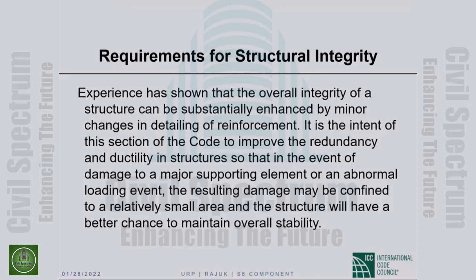Okay. In footings or pile cap, where should we place the temperature or shrinkage reinforcement? In the top of the footing or pile cap? I specifically covered this; the answer is the same as for mat foundation. It is up to you. If you think it will do the most good near the top surface, that's where you will place it. If you think the bottom surface will do you more good, that's where you will place it, or you can distribute it between the top and the bottom.